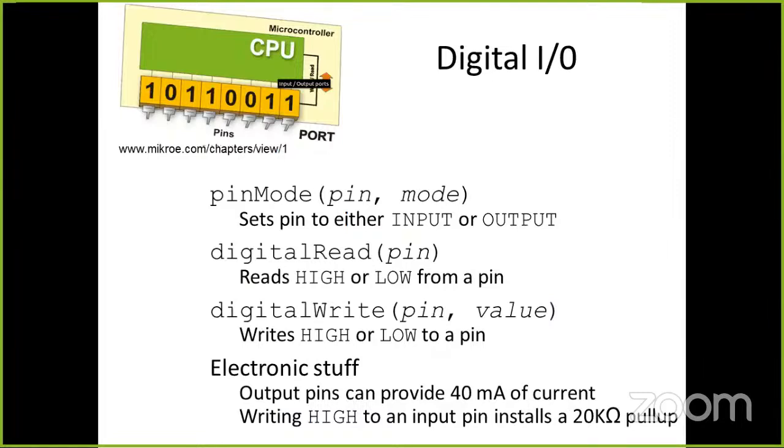This is the programming structure, how we have to write code in the Arduino. We have to write in this format: pinMode, where the M should be capital. This is a syntax, meaning we have to write it in the same way. If we make any mistake while writing the syntax, there will be a programming error in the code. pinMode means we have to define which pin we are using in the Arduino.